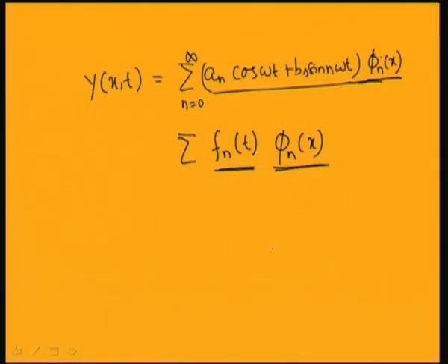In the exact method we find the eigenfunction of the system, which satisfies both the differential equation and all the boundary conditions. Instead, I can take some function which satisfies only the geometric boundary conditions, and then find f_n(t) which will best fit the differential equation, the other initial conditions and the forcing function. In that way I can approximate the system.